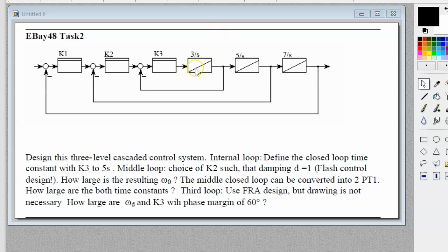Note that each integrator has a fixed phase shift of -90, and with three in series connection you have a total phase shift of -270. With one single loop it is absolutely impossible to stabilize this system, because a PID has a maximum of +90, ideally +90, and then you have a total phase shift of controller +90 and 3 times -90. So finally you have a negative phase shift of -180.